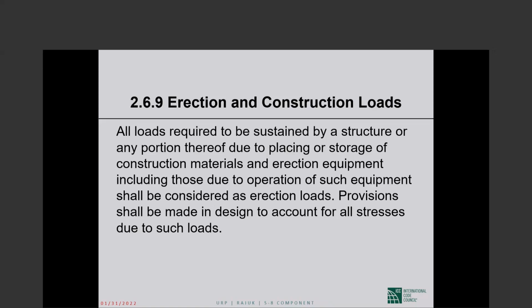There is a lot of pressure from the contractor to remove the formwork as soon as possible for reuse. So while the concrete is still green, I don't know, 4 or 5 days after construction, you will remove the shores, remove the formwork, but then we invariably reshore. We now install the shores directly supporting the concrete slab.